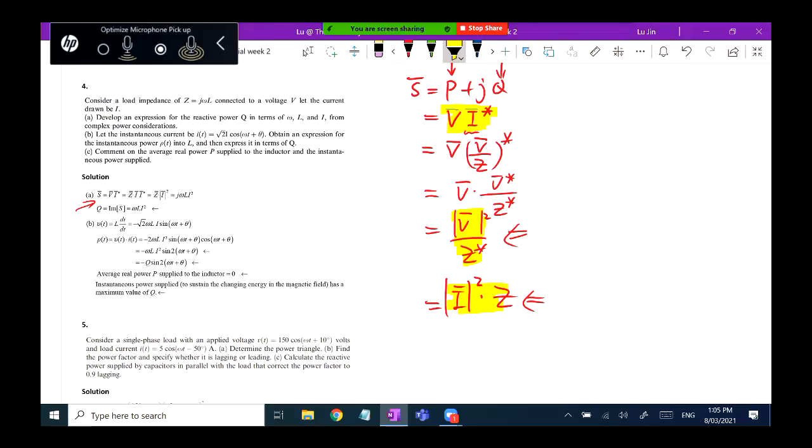Yes, good question here. For all the power calculation, we must use root mean square values only. We should never use the maximum amplitude of the cosine function of current or voltage to calculate. Never. Always root mean square values. Thank you for your reminding. Okay, after we understand the background of this, I'm going to wipe off this stuff